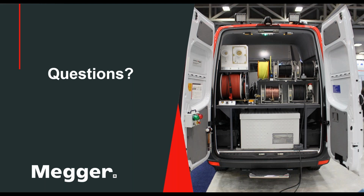Okay, so as stated before, branches require the ability to isolate from some middle point of that said branch. But if you cannot isolate from that branch, what we say is you can try from each end. And if the fault is close enough to your hookup point, meaning let's just say it's a 4 branch, 5 branch, however many branches you decide, and if you cannot isolate from one middle point and look in each direction, you could try from each end. If the fault is close enough to your hookup point, the radar/arc reflection might give you a good enough trace to give you footage, but depends, as stated before, on how close the fault is to your connection point.